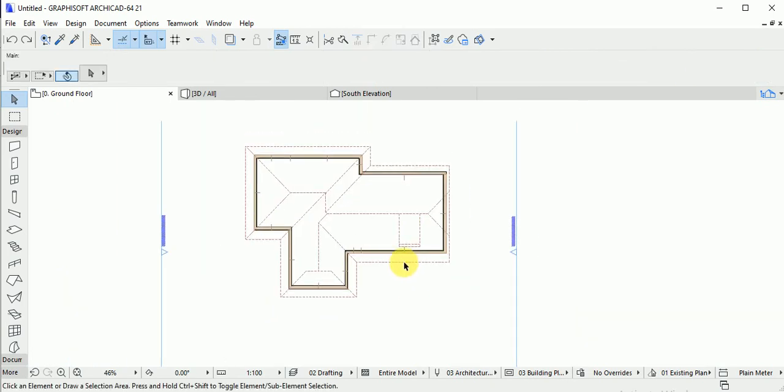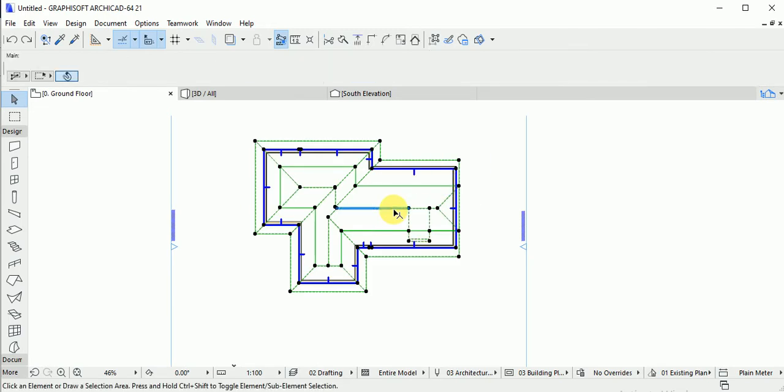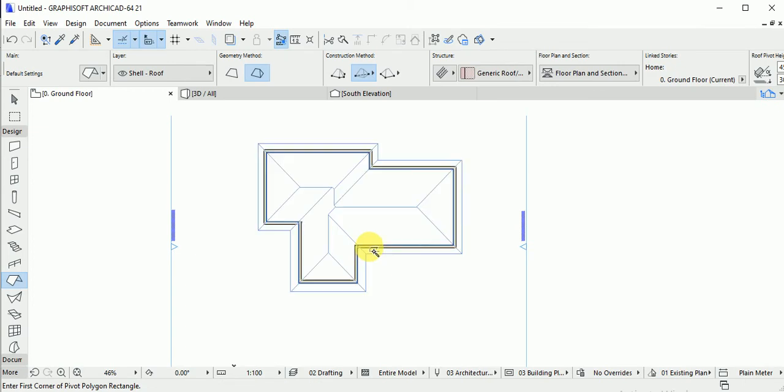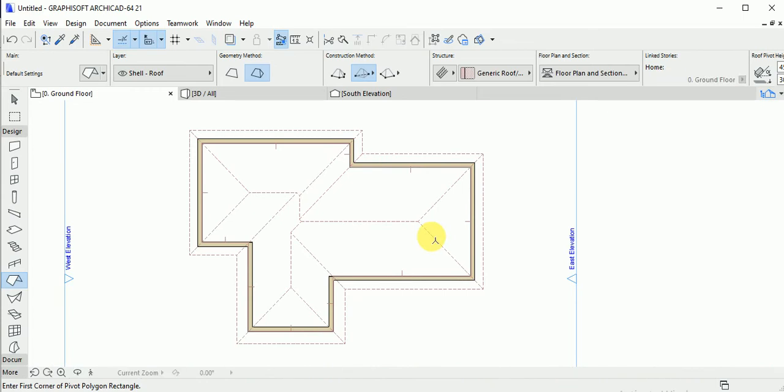Now the next explanation, I showed you how to do it. Now in this particular one, let me delete this roof. You can still click your roof, you click your space bar. Now your space bar is showing you the magic one. This is the magic wand. Once I'm clicking the roof, as you're clicking your space bar, because you touch the roof, the wall, it will show you exactly the shape of the roof. That's how you can draw a roof fast. Then you click it. If you want to draw a roof that is irregular shape, you do the same thing. Now you're having the same roof.